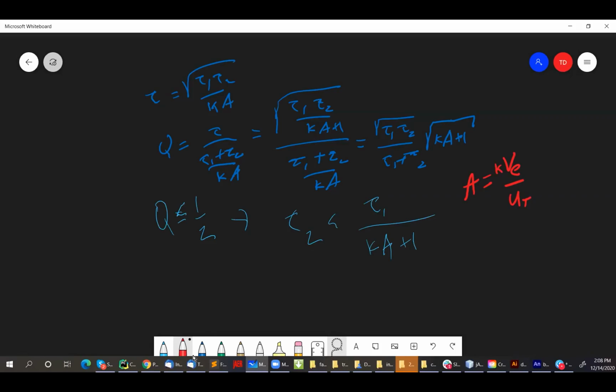And why did we assume that gain for the amplifier? Because the model of the transistor was this. Here is the drain voltage. Here is the drain current. The model of the transistor is like an ideal saturation current. This is ID sat.